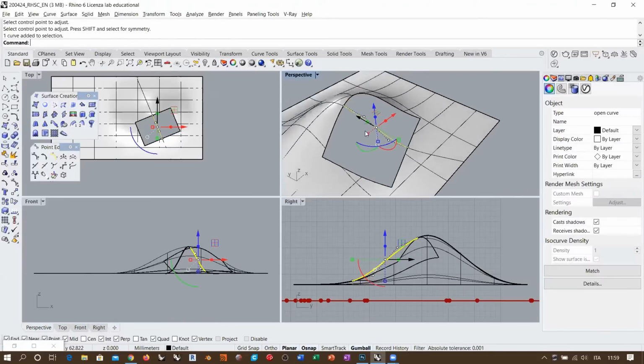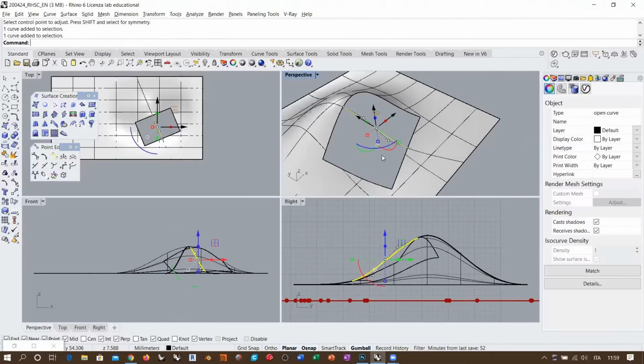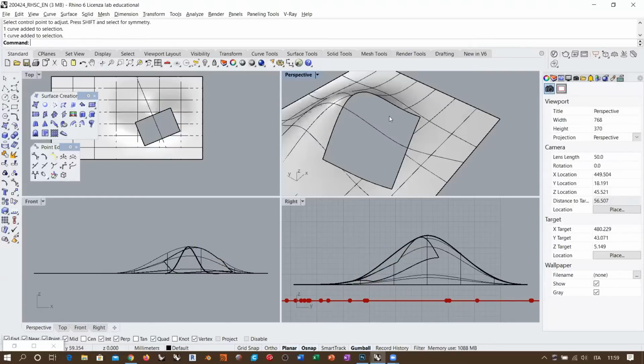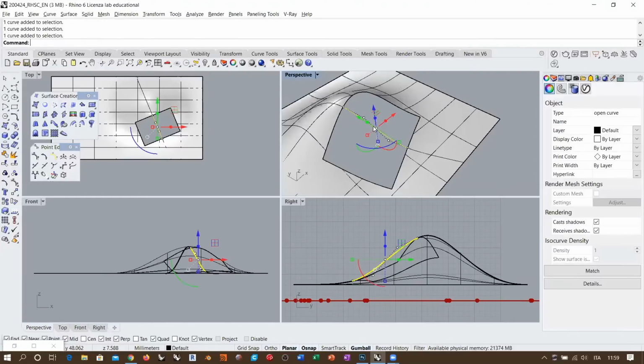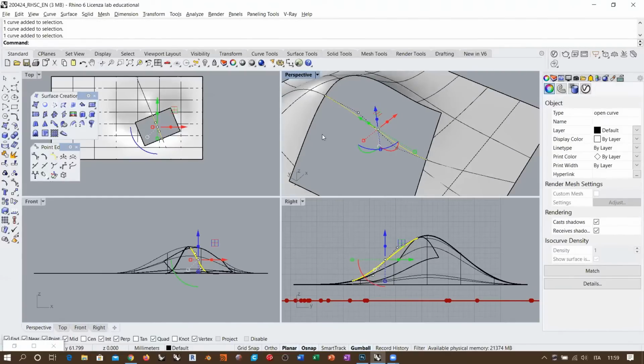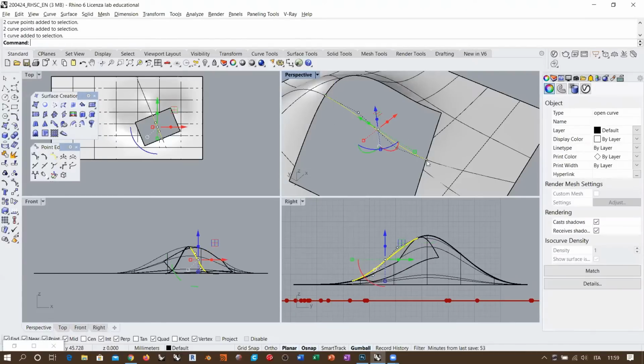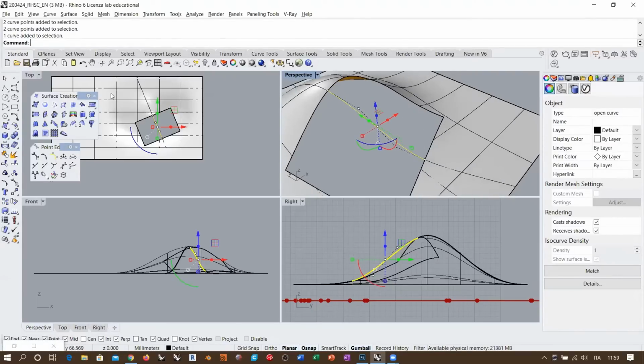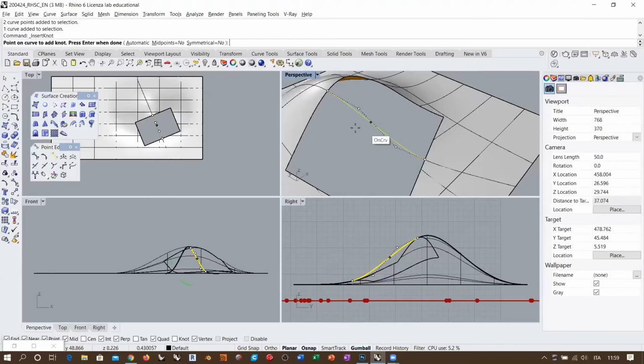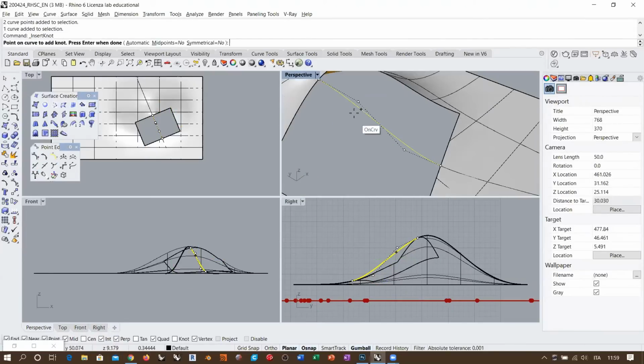Once I have this curve, if I need my surface, which is going to use this curve, to be curvature continuous here and here, I need the surface to be based on a topology that not only has 2 control points and 2 control points, we need 3 control points here and 3 control points at the end. So I go along this curve and start to add knots to it, for example 1 knot here and 1 knot here.